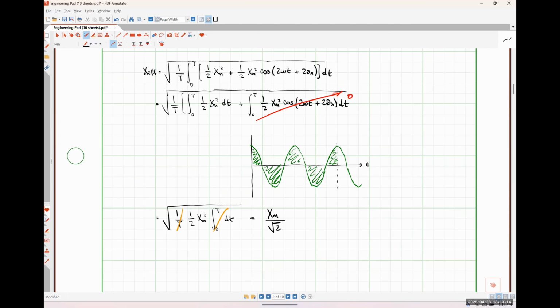Regardless of where we are in the world, what time we do anything, the effective value of a sinusoid is just the magnitude divided by the square root of 2, which we all should remember from circuits 1. So now let's see if we can wrap our heads around what's going on when we have a multi-frequency circuit. Okay.